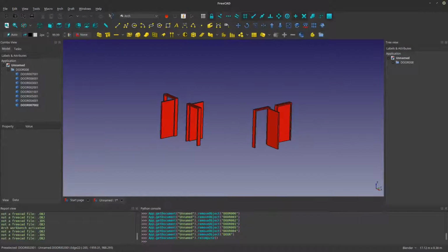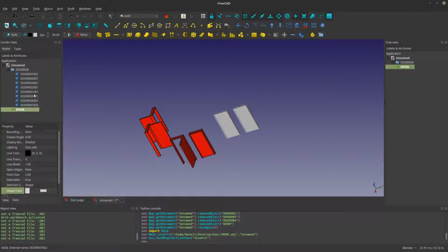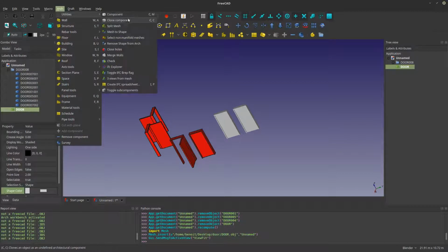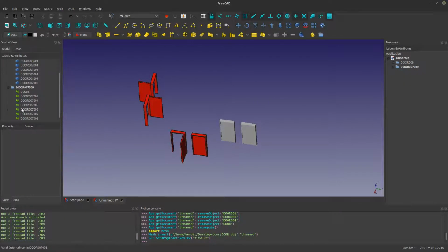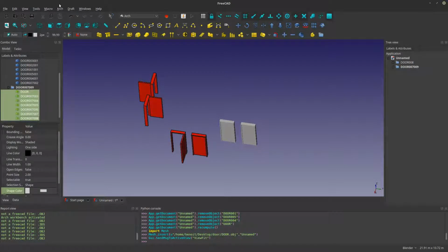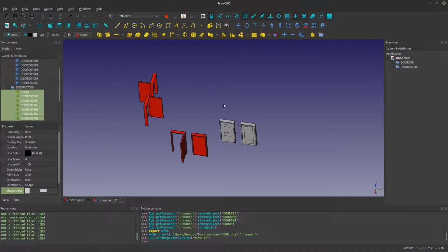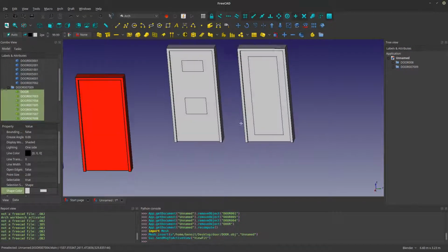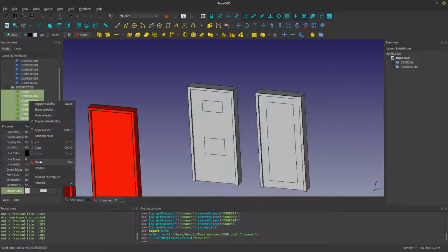Now I'm going to drop them in here again, drop my doors, select, I have two doors there, one mesh. Split the mesh once again, now I have the doors. Convert the doors, architecture, convert that. Okay, so now delete the mesh.